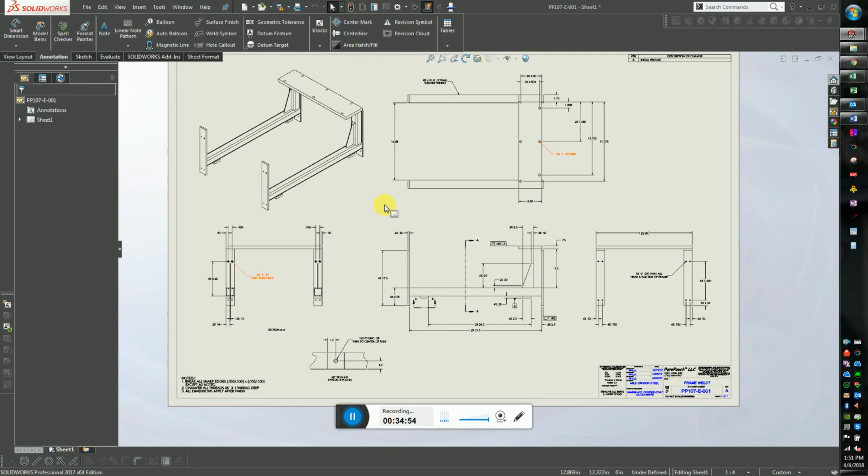I don't think there is really an answer, but maybe sometimes it might be worth thinking about how the answer is different for a mass quantity piece versus a one-off piece, which is what I know that you do. Yeah, because what's the trade-off with high production? You want to keep your costs as low as possible, and with a one-off prototype, you're paying big money for it and you know it, so it better be right. Based on the results of that, you can probably say, all right, we don't need 5 thou here, we can get away with 20 thou, and it still operates 99.9% of the time.